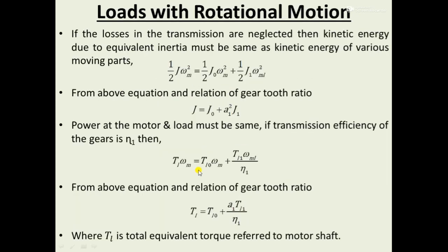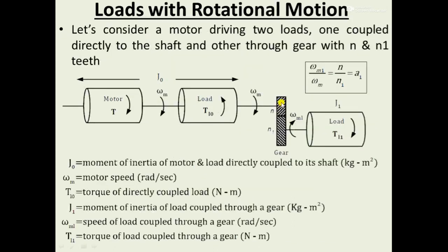Next we have to find out the relation for equivalent torque. In order to find out the relation for equivalent torque, the losses in this transmission system are taken into consideration, although they were not taken into consideration while obtaining the relation for equivalent moment of inertia.